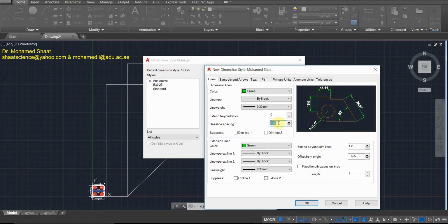So it is advised to consider a reference number, which is 5% of the maximum dimension of the drawing. The maximum dimension of the triangular shape here, the maximum height or the maximum width, is 1000. So 1000 times 5% gives 50 millimeter. Then this number is gonna be 3/4, or 75%, of this 50 millimeter.